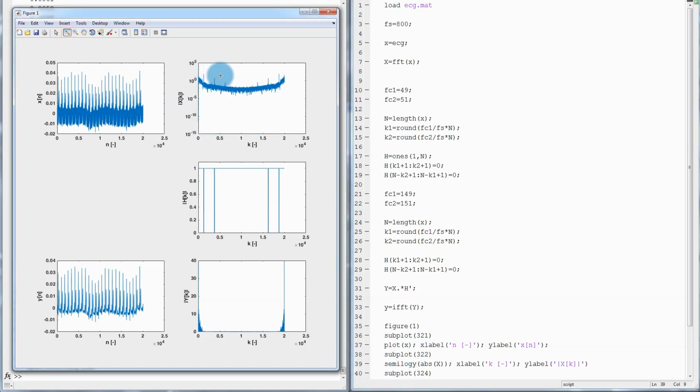It sometimes helps to scale this a little bit. And now I can very clearly see in the spectrum both strong parts, which is this first harmonic of the power noise interference, and these very weak parts, which is that ECG at very high frequencies. And for example, there is something which you were not able to see with linear scaling on the vertical axis.